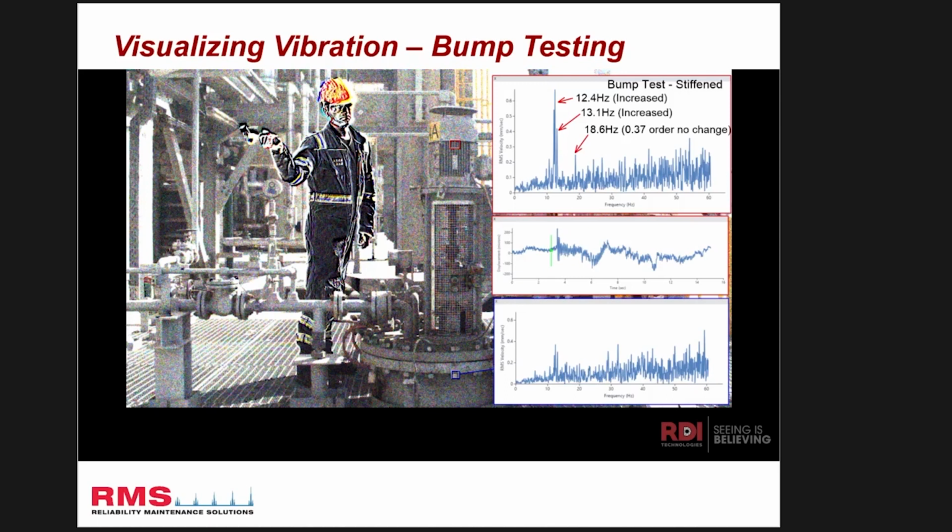Not with the camera, because that needs to be stationary, static, because you just want the response of the impact of the hammer. If that's rotating, it's got a forcing function of imbalance or something like that in there anyway, and then you'll have another frequency to deal with. So the idea of a bump test to work out natural frequency is to take away that frequency and just leave the force of the impact and your resultant.